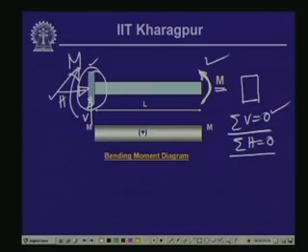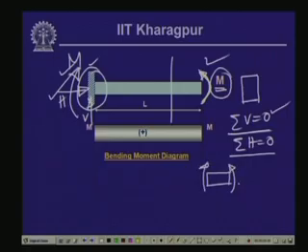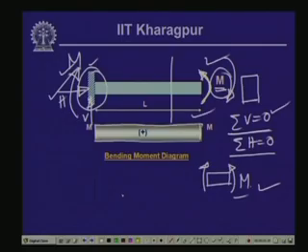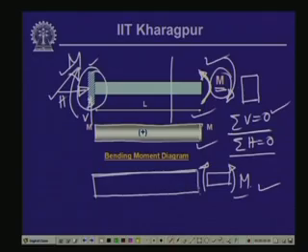The only thing is that the moment will be equal to the externally applied moment. At any section we take, if we draw the free body diagram, the value of the internal moment equals the external moment, and that is how we get a bending moment diagram which is a rectangular one. That means, everywhere we have a constant moment. If the moment direction is reversed, in a clockwise direction, we will have exactly the same result, only the moment will be negative instead of positive.